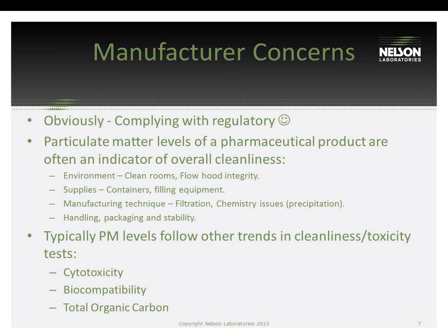As manufacturers, obviously we're concerned with complying with regulatory concerns and requirements, but also particulate matter levels of a pharmaceutical product are often an indicator of cleanliness from your environment, where the product may be manufactured, from supplies, whether that be supplies in-house or provided by a third-party manufacturer, manufacturing techniques such as filtration of the product, or any chemistry issues that may exist, such as precipitation of the product under certain circumstances.